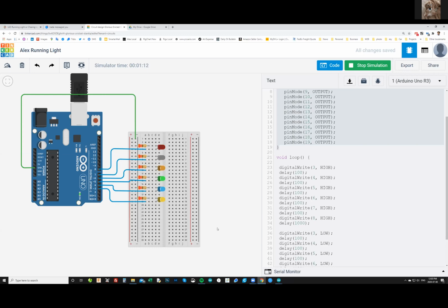If you want to be super advanced, try to simulate physics. Imagine the light is a ball, and you want to have it bounce like this, bong, bong, bong. You can even simulate a little acceleration and deceleration as well. You can change the delay with which the ball propagates from one LED to the other. So when it goes higher, it gets slower, and then it goes down and goes super fast and goes back again. If you're up for a challenge, try to challenge yourself this way. Play with the delays inside your main loop, and try to make it look as physical and realistic as possible. Pretend it's a computer game, and you make it like a ricocheting ball. If that's not too much, the program minimum here is for you guys right now.